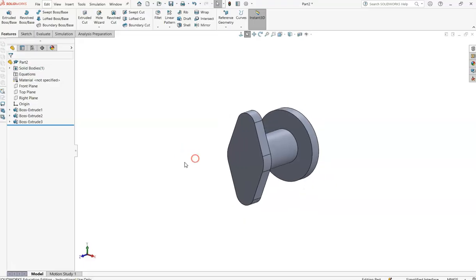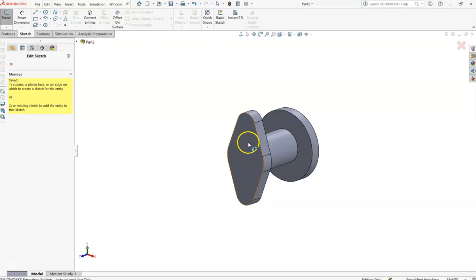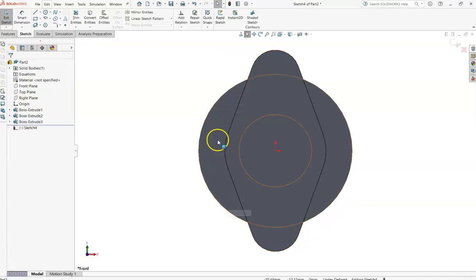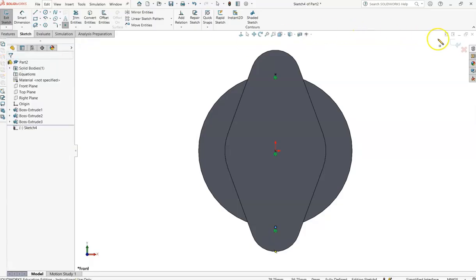So here I want to add in my different sketch points or my work points. So I'm going to go to the Sketch tool, and I want to select Sketch, and I'm going to click on this front surface first. Now this is pretty easy because we already have this drawn. So I'm going to use one of these work points up here, and it's going to be in the center of this arc. If I just move my mouse over the arc first, I'm not clicking, I'm just pausing on that line. You can see the center point pops up. I'll put one there. I'm going to put one on the origin, and I'll move over here and then put it back on there. Okay, I'm going to hit the green check, and then I'll hit return. So that's the first sketch.